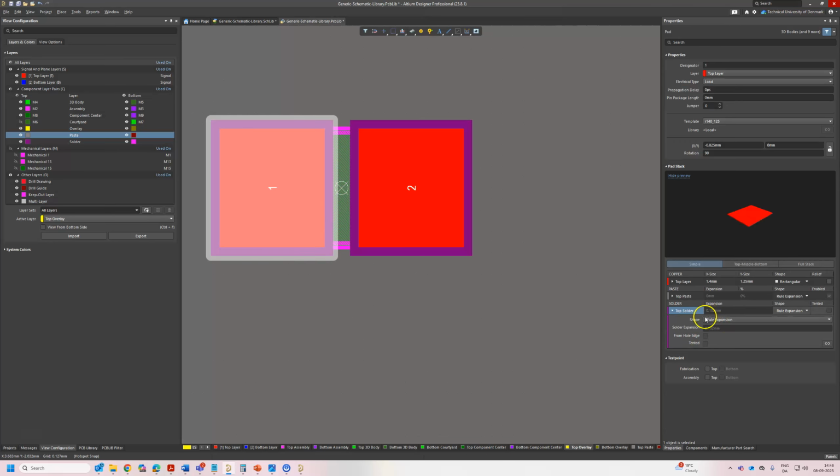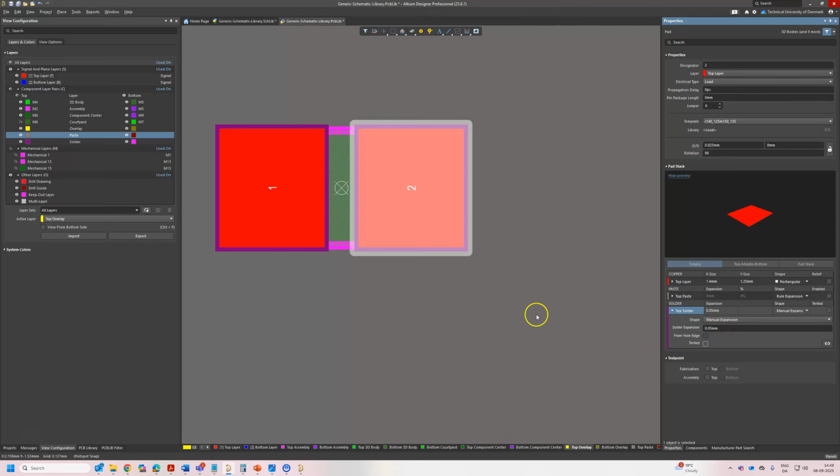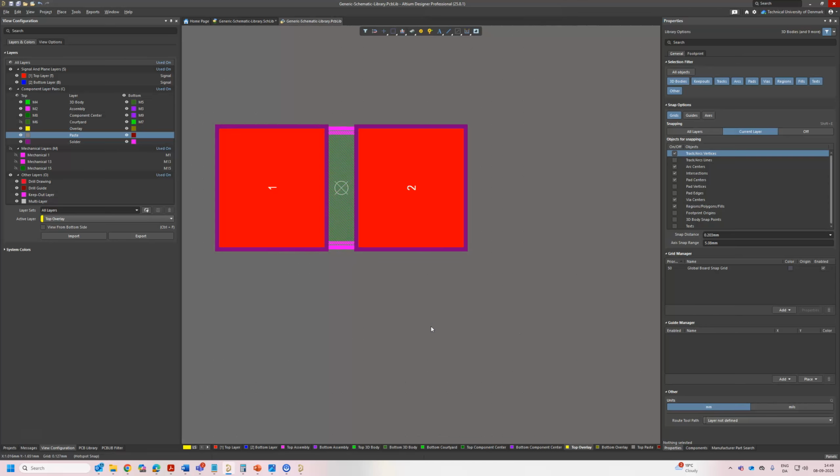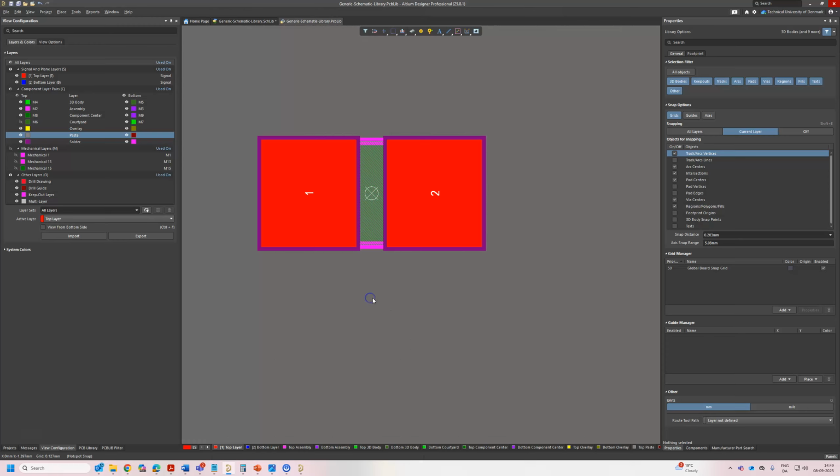The only thing I need to change here is the solder rule, which is 0.05, if you remember. Then manual, 0.05. Control S, and now we have our capacitor here. So you should do it correctly from the beginning. I suggest to change the color.